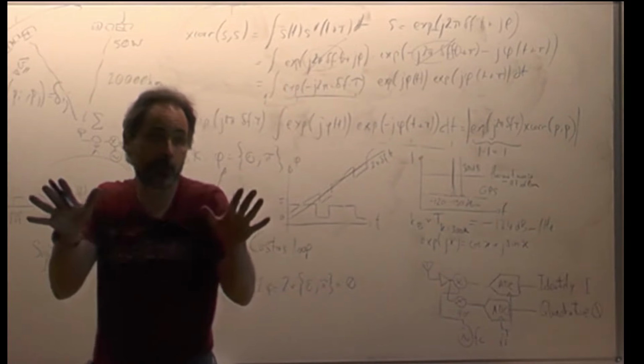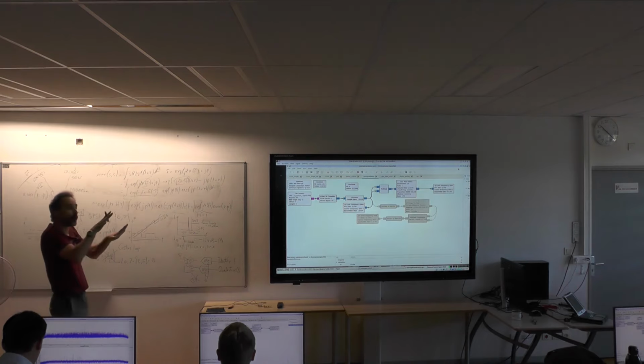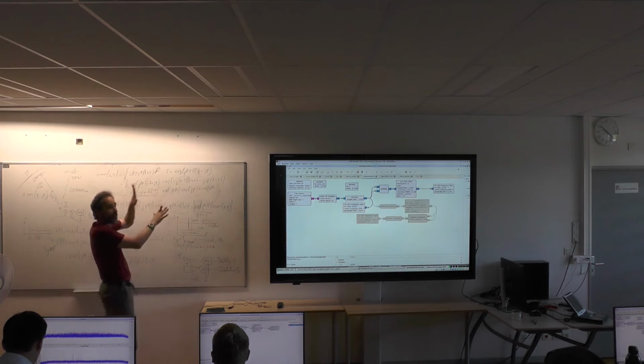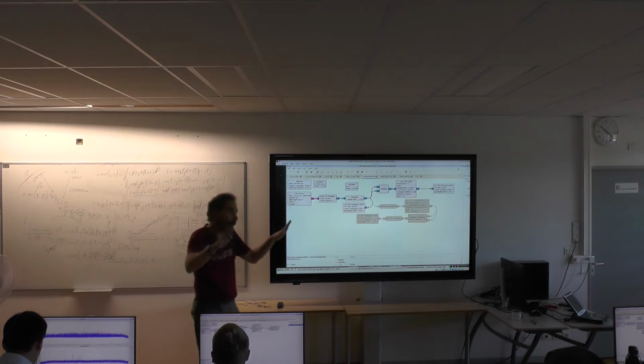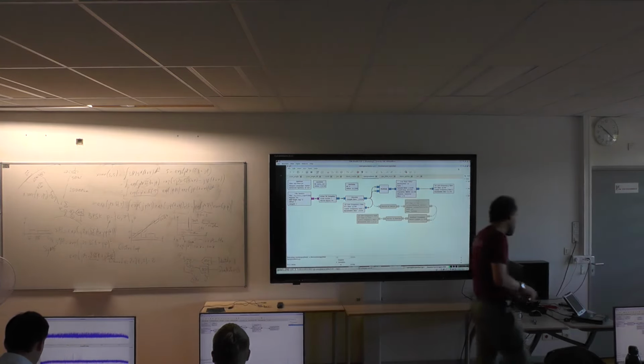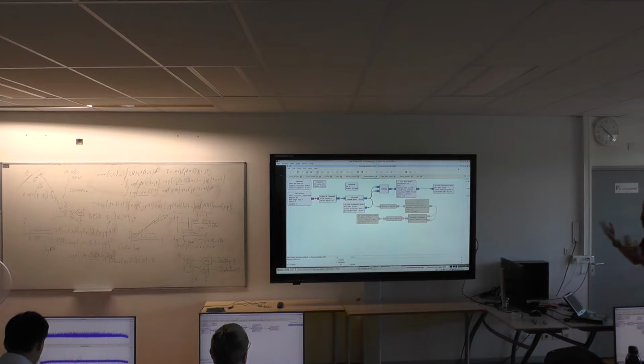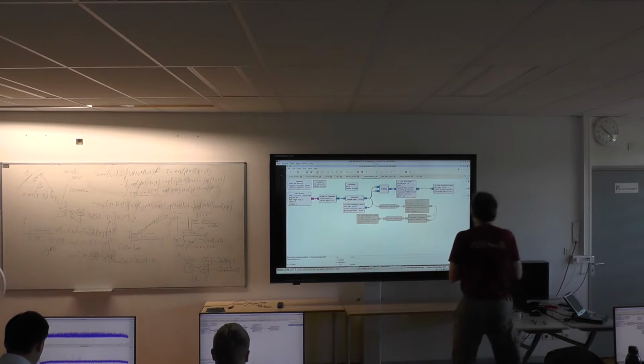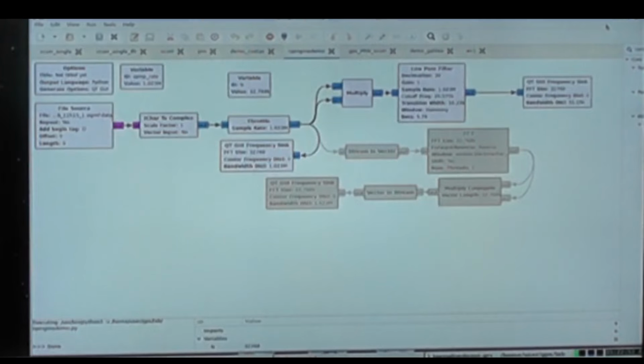So you see that the magnitude of the autocorrelation is equal to the magnitude of a pseudo-random sequence, because you're looking at the self similarity, and your signal is shifted by the Doppler shift at time t plus tau. So as long as the Doppler shift is not shifting too quickly, the autocorrelation will give you the repetition rate of the chips in the pseudo-random sequence.